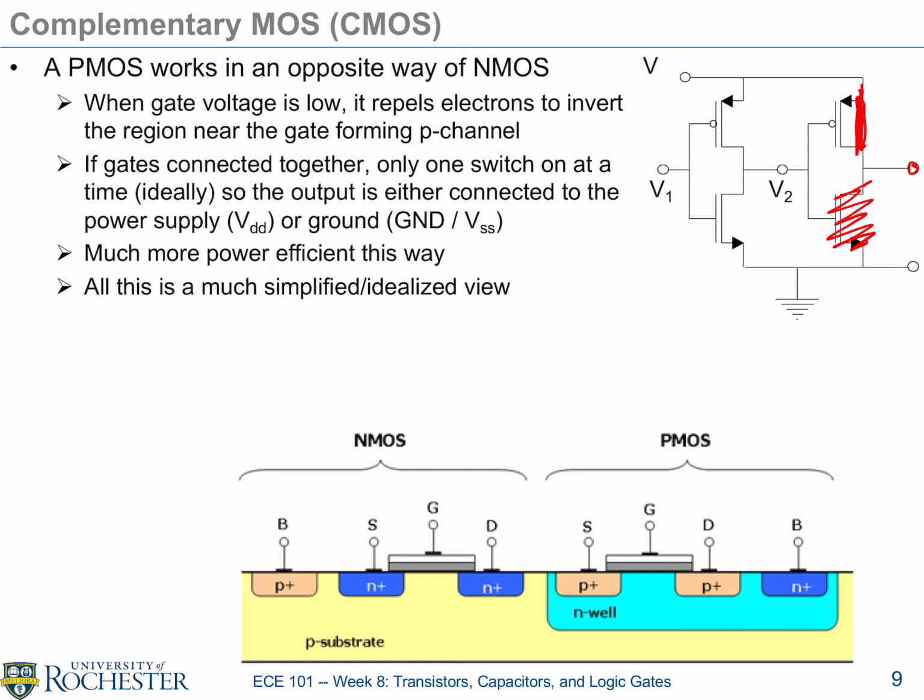And in fact, in the early stages of the computer age, we had NMOS computers where we only use one transistor, so the chip is perhaps smaller. I may be wrong in that, but that may be an advantage in some sense. The chip is cheaper to make, but it burns more power because it doesn't have this property that at any time only one of the switches is on, so there is no conducting path from power to ground for any long duration.